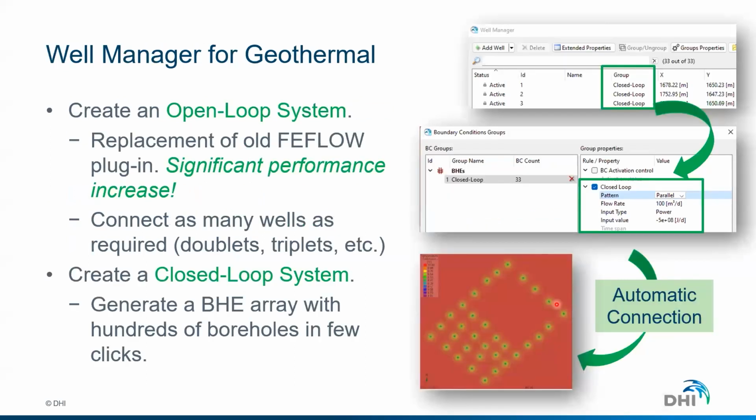So coming back to the well manager, what we have done is we introduced two operational rules, which are called open loop system and closed loop system. In the case of the open loop system, this rule will entirely replace the old plugin called open loop plugin. If you have been working in the geothermal market with FEFLOW, this plugin has existed for more than 15, 20 years. It's an old implementation which was not up to date. So we have reinvented this and implemented it directly into FEFLOW, so you don't need to use the plugin anymore.